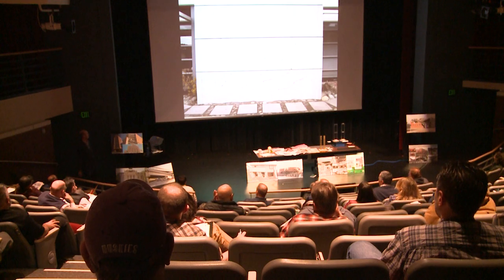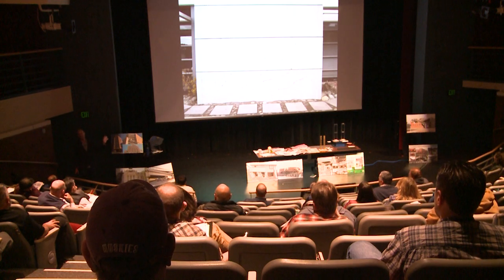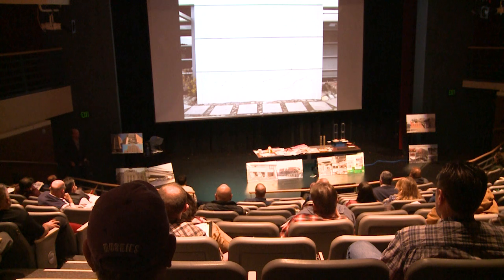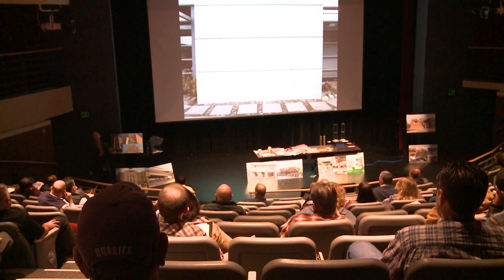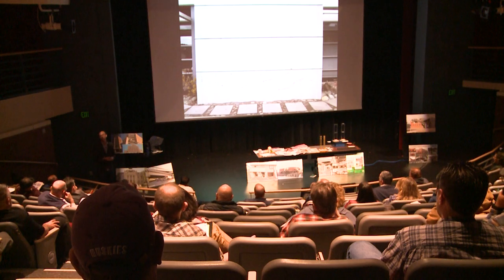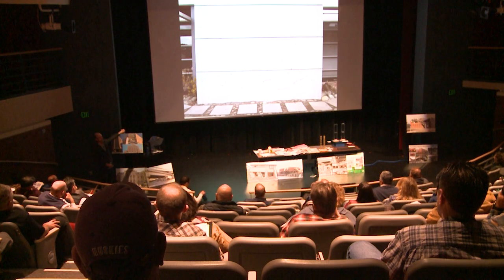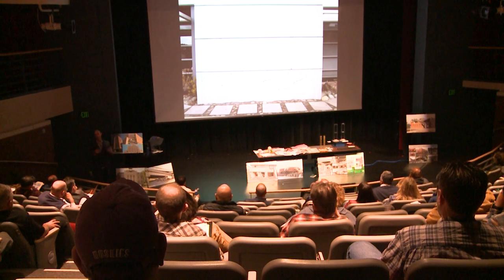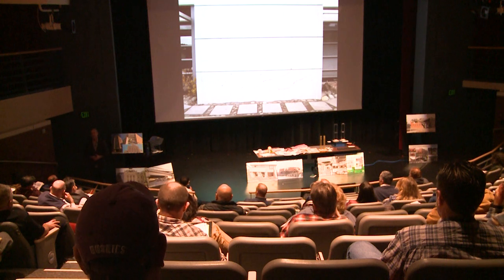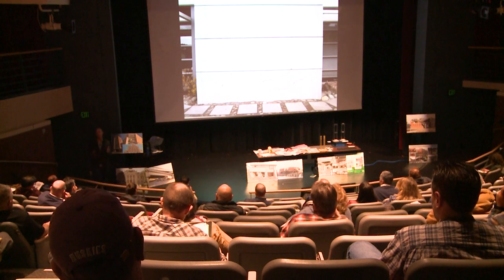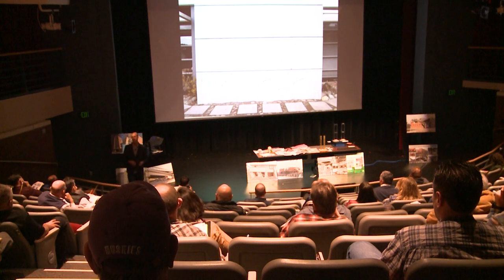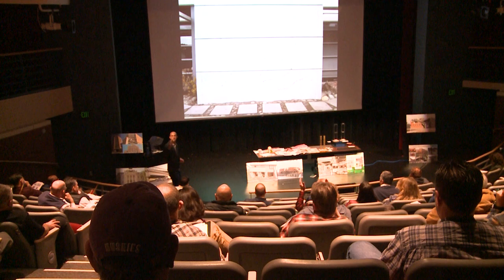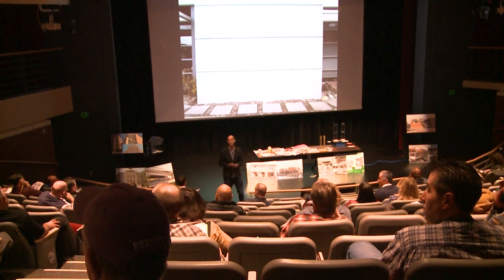Yeah, I probably should have addressed that. I think what we're seeing is a solid reinforced concrete shear wall, so the structure and the confined concrete underneath the reinforcement is all consistent, but for architectural purposes, it's got the stamp and coloring and a little sort of lip and protrusion. I would consider that exterior to the functional structural part of the shear wall itself. So it's not 3 walls, it's 1 wall with some pretty little lines on it. Kind of a rabbit trail.